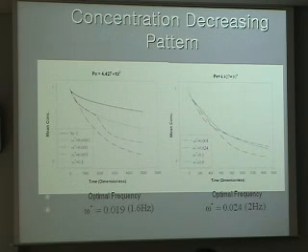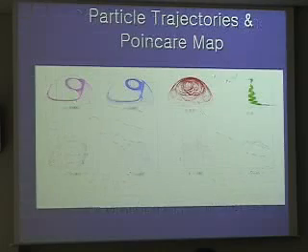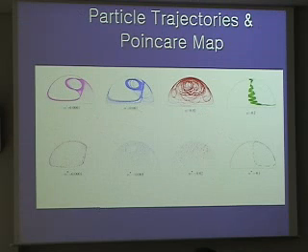By using that kind of mechanism, when we apply optimal frequency forcing, we could maximize the mixing efficiency. And as you can see here, when the forcing frequency is not just right, too small or too high, in that case, there is almost no mixing.